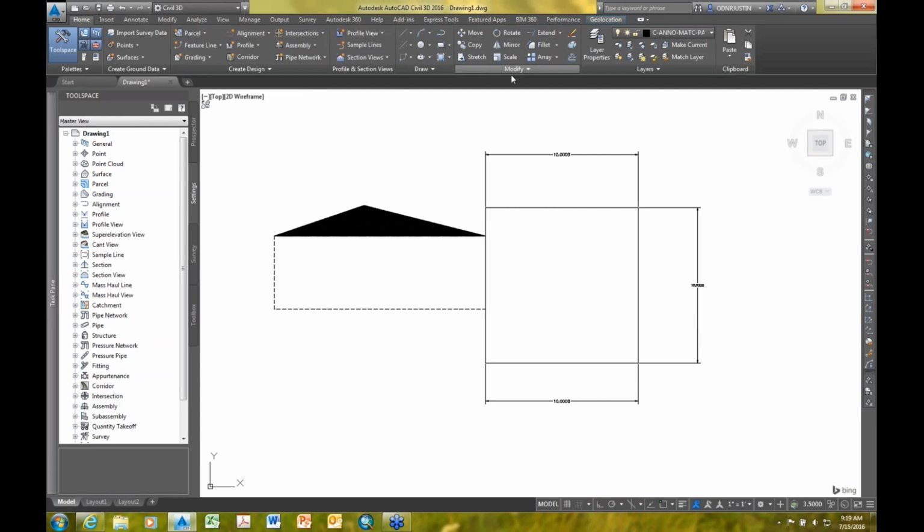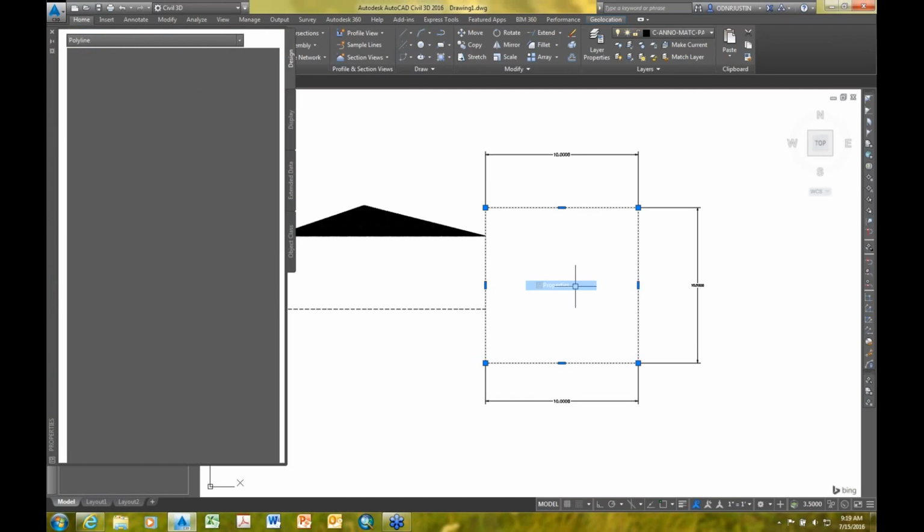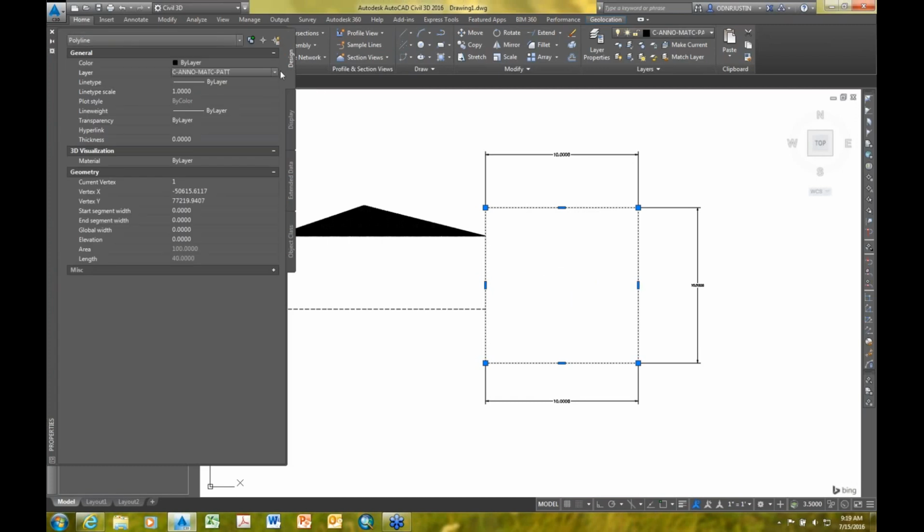Before we go, there's one other concept I wanted to introduce, and you reminded me of that when you mentioned it, which was layers. And we'll talk a lot more about styles and so forth in the next class. But when I draw anything, as far as basic line work, I should be doing that on my zero layer. The zero layer must be in every drawing.